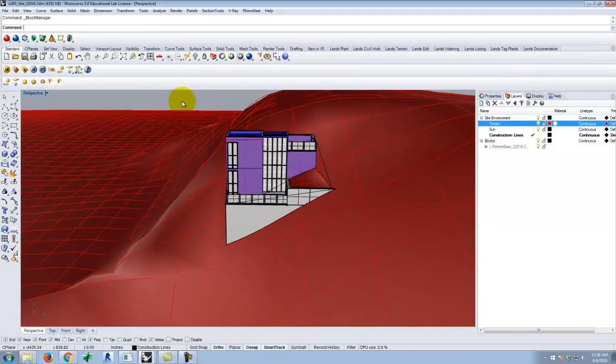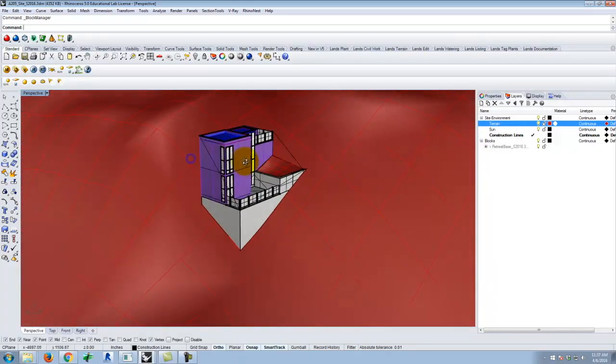The other thing that you'll find when we get into lights and lighting is that if you have a version of Rhino on your home computer and you don't have V-Ray installed, when you open your Rhino file, sometimes, and it's not a predictable sort of thing, the Rhino file will corrupt your V-Ray lights if you don't have V-Ray installed at home. So by doing this, because the lights are always going to be in this scene, you can safely open your actual building and make all the edits you want to it, and it will never corrupt any of your lights. Okay? It's just something that I'm forewarning you about. We'll talk more detail as we go a little bit further along.